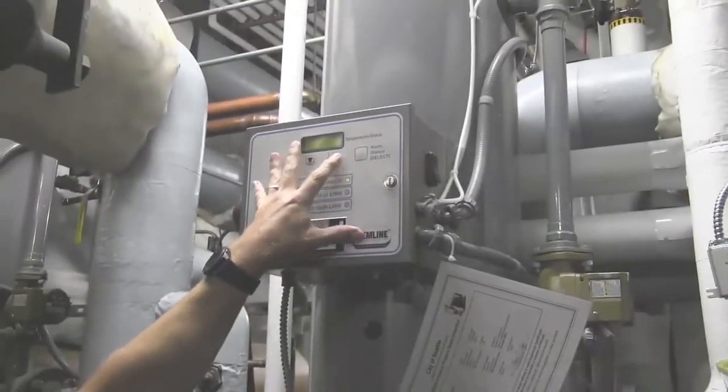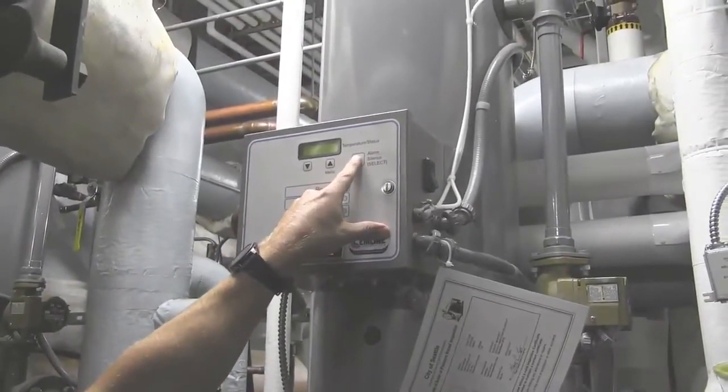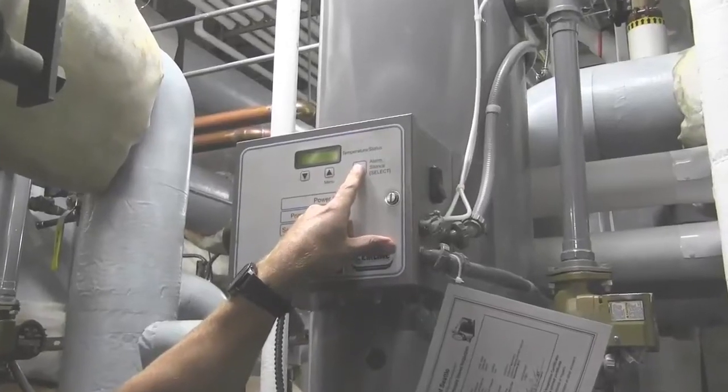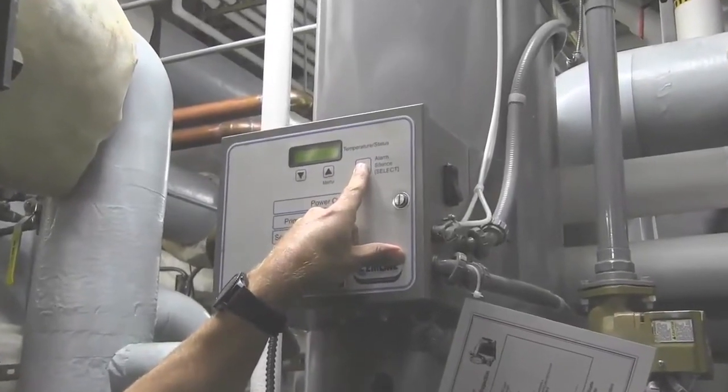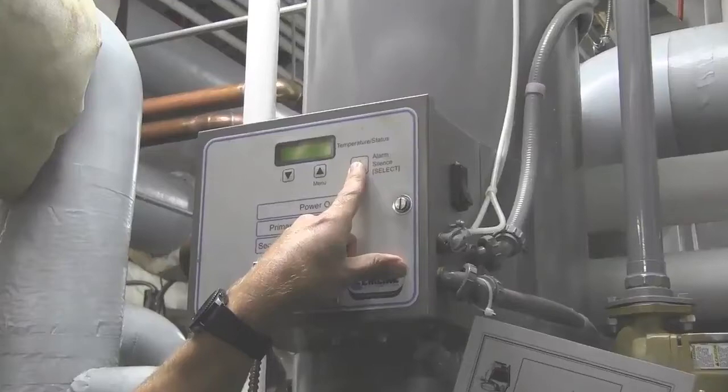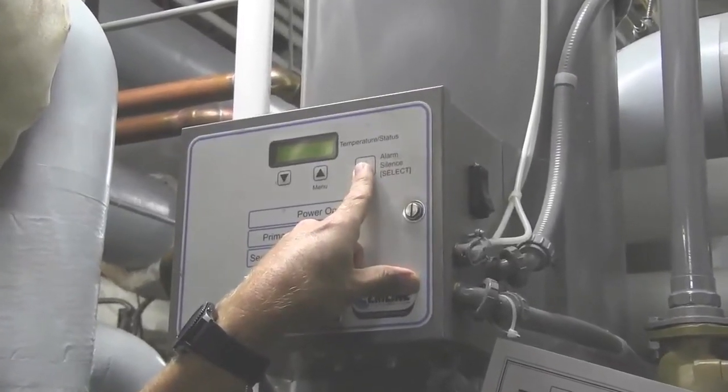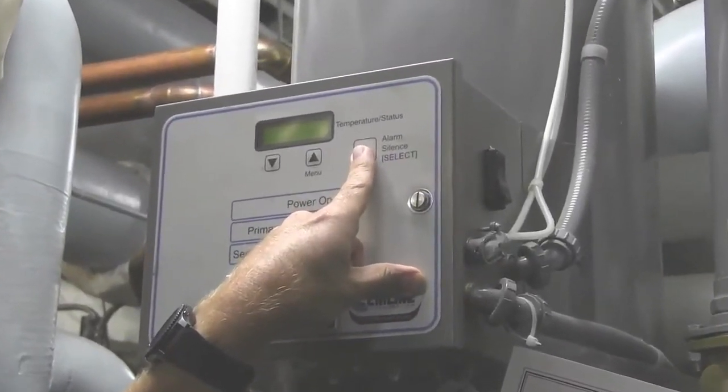High limit number 2. So we would do that. That's up to 150 degrees. We can make that adjustment as needed also, because I don't believe you guys have any mixing valve on the outlets of these, do you? Mixing valve, you don't temper this water down.